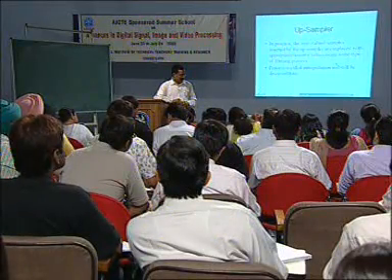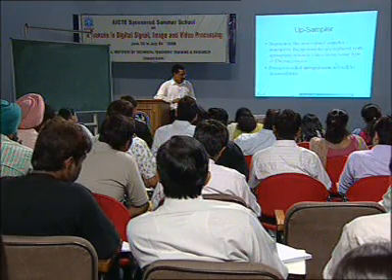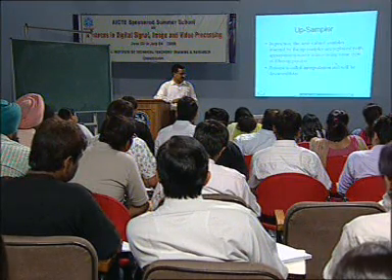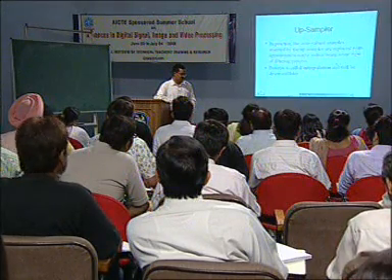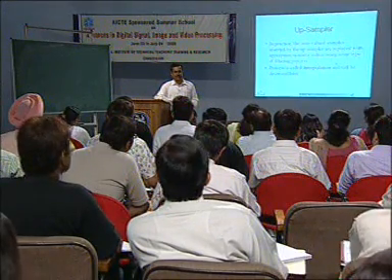So, here in practice we never want to introduce so many zeros at the output of an upsampling device or upsampler. The zero valued samples inserted by the upsampler are replaced with appropriate non-zero values using some type of filtering process.